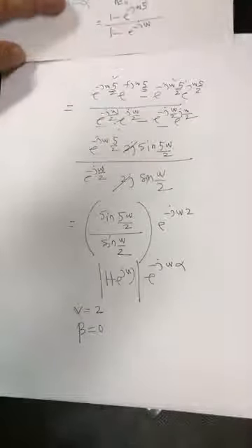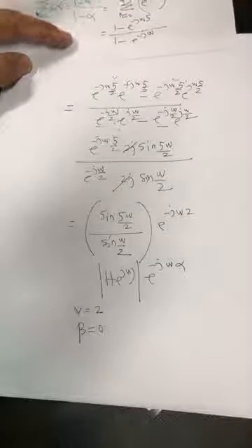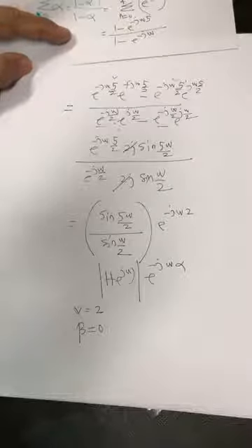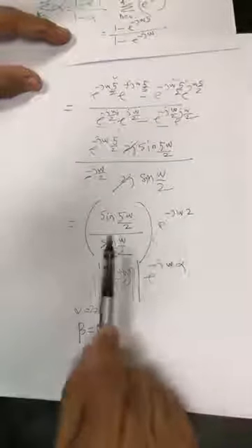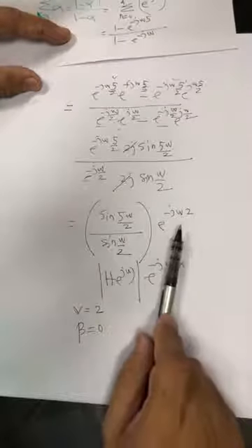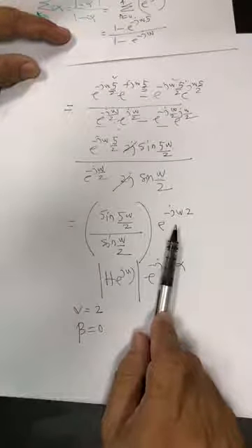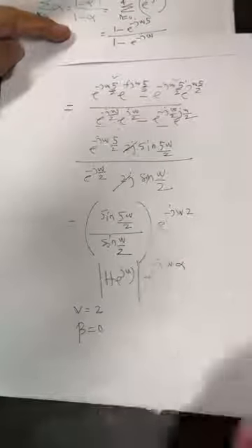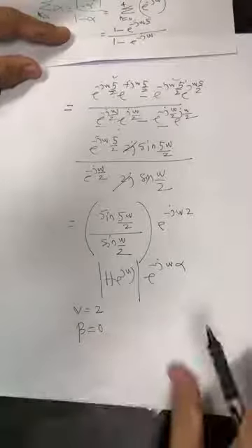So this is yet another interpretation of linear phase FIR filters: all linear phase FIR filters can be brought to this form, with a real magnitude and a phase which has alpha omega plus beta. So this is one interpretation. The other, I have told you, is that there are clusters of zeros that you see in this. With this, we are actually done with this chapter, except one thing is left, and I should also cover that.